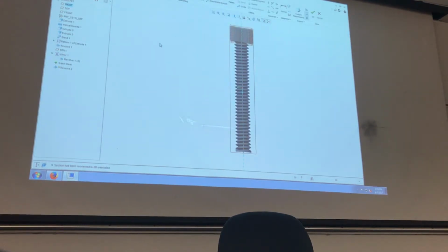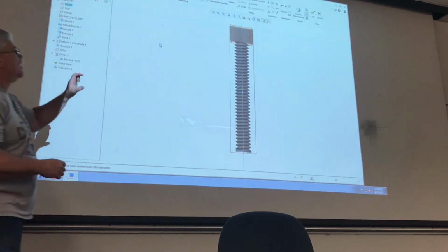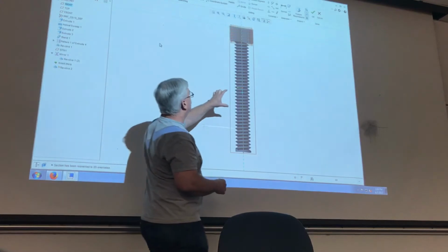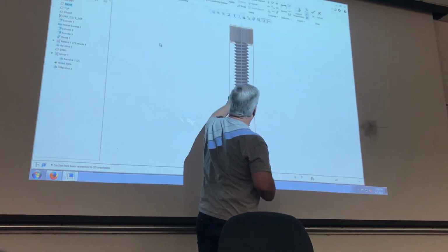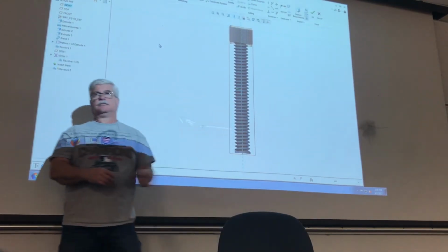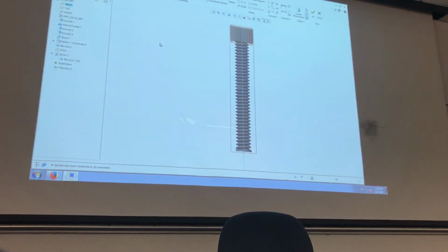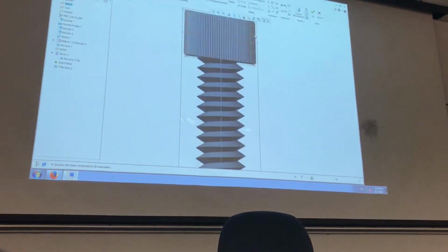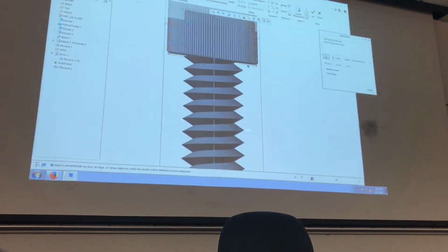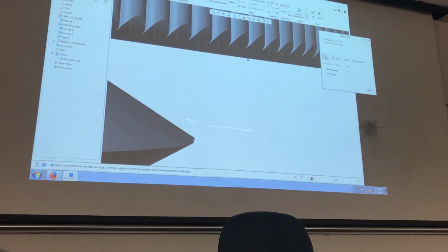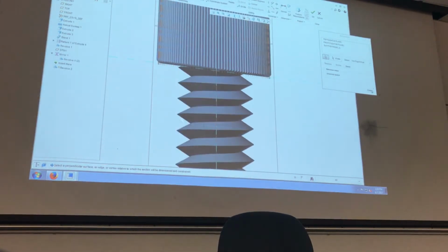Now, the dimensioning on a screw, when it says 1/4 by 1, that 1 inch part of it is from the bottom of the head to 1 inch of thread, not including the head of the screw. Okay. So what I'm going to do is use the bottom of the head as a reference. So I'm going to add another reference in here. So I'm going to zoom in here, get that horizontal line right there. So now I have a reference to use.